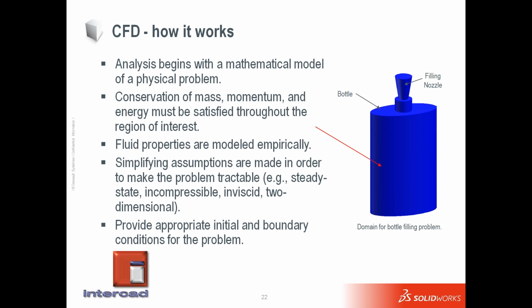Let's see how CFD works. This sort of analysis begins with the mathematical modeling of a physical problem. For example, if you have an exhaust or a domain for a bottle filling problem, this is how you define it. First, you need the geometry and you bring it to your CFD studies. What you have to know is that you are going to solve the conservation of mass, momentum, and energy equations and satisfy them through that whole region.